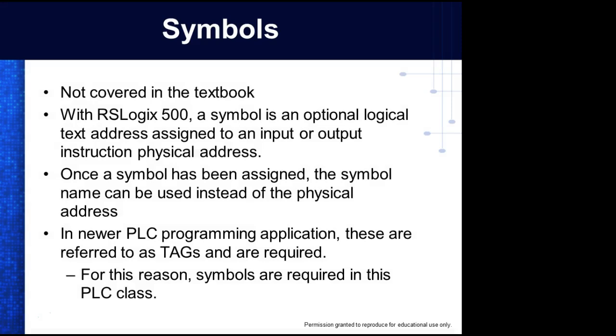Symbols. This is what we're going to require. Symbols are not covered in the textbook. With RSLogix 500, a symbol is an optional logical text address assigned to an input or output instruction's physical address. What's nice is once you give it this name, you don't have to remember the physical address. You just have to remember the name.